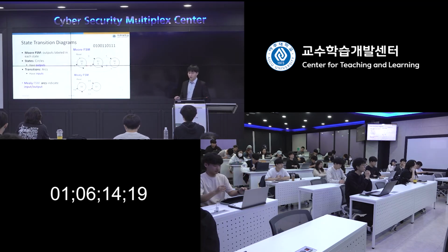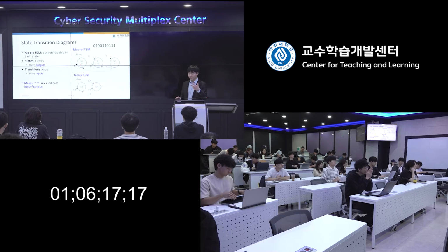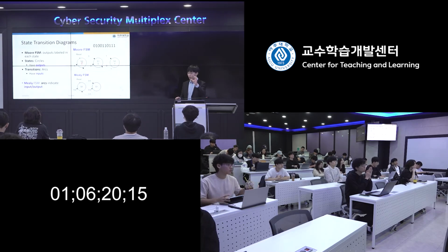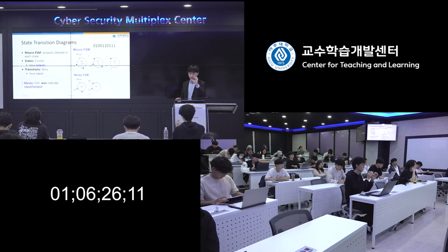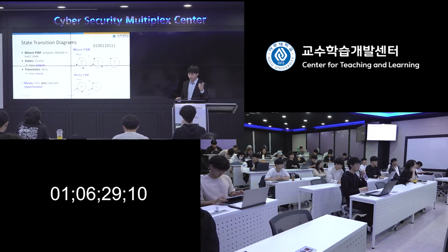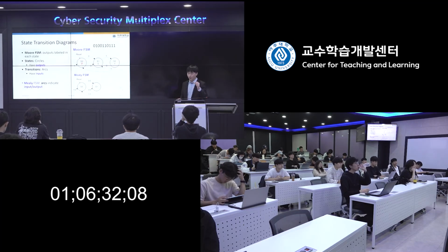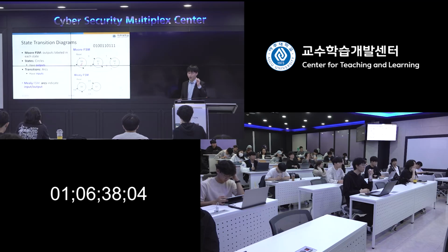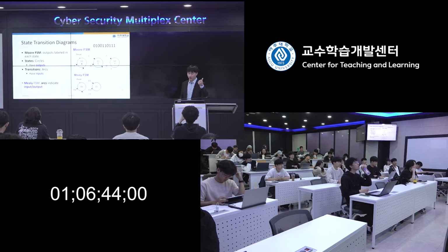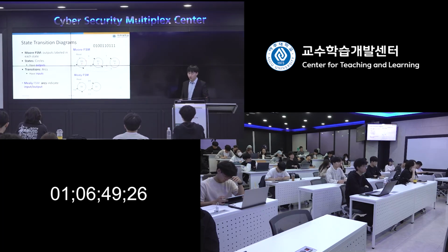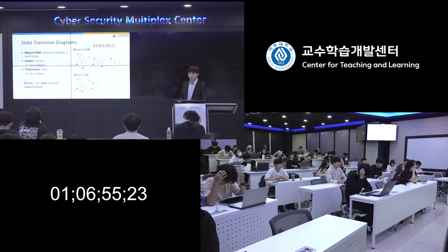For example, here, this is Moore FSM. Inside a circle is the output, which is whether it smiles or not, right? The input is on the arc. So for this state S0, starting from the original state, it did not smile. That is the output of that state. Now we just need to check the next state. The next input is 0 or 1, right?